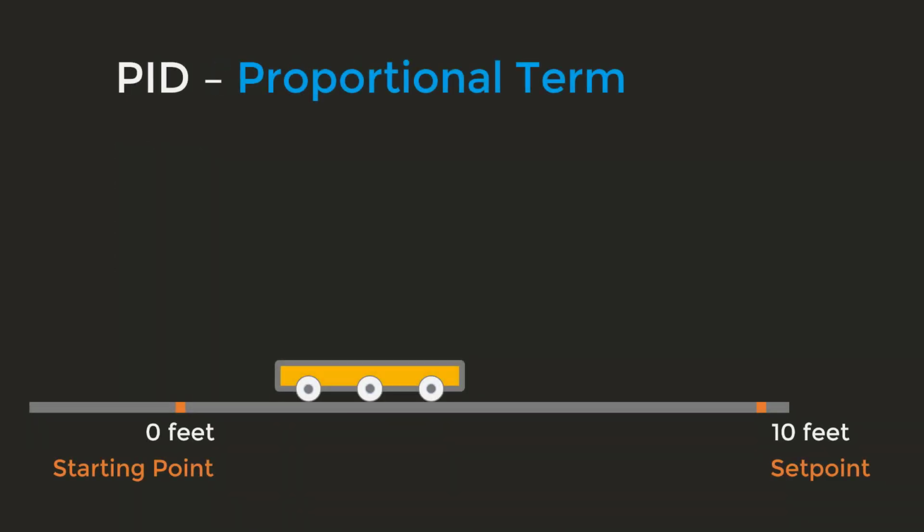The gradual slowdown can be done using the P term in PID. From the encoder sensor on the wheels, the robot can know the distance between the set point and where the robot is at. Let's call this the error. We can then tell the robot to have less and less speed when we have less and less error.